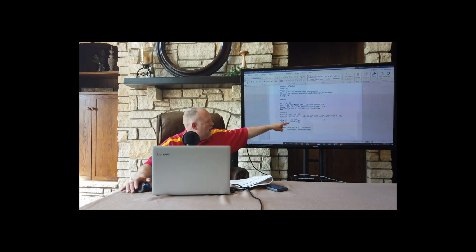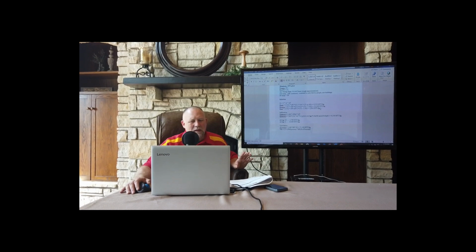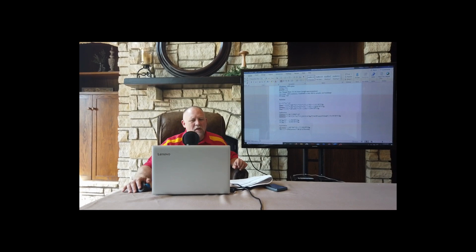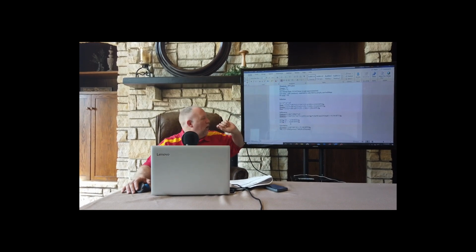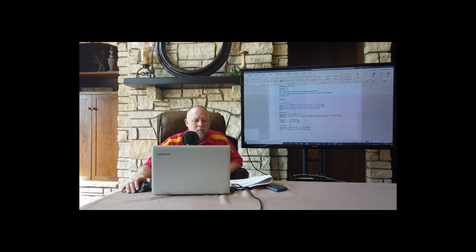Look at that value now at 2 air changes per hour. It's worse than everything else. And it's almost worse than all of them combined if air changes per hour was actually 2. That will have a drastic impact on your building, on your comfort, and on your energy consumption.